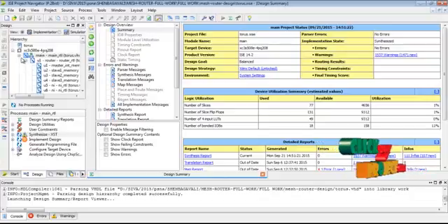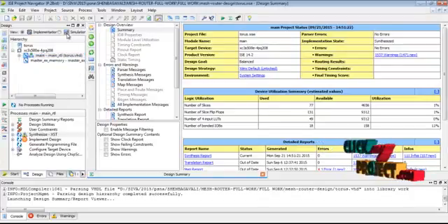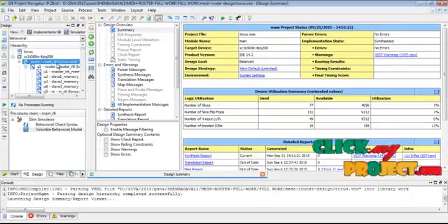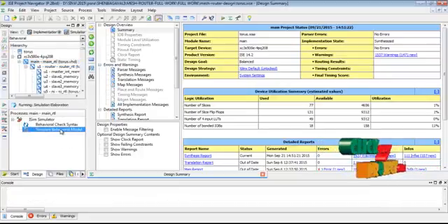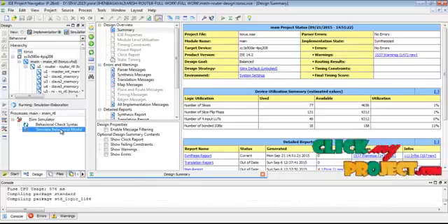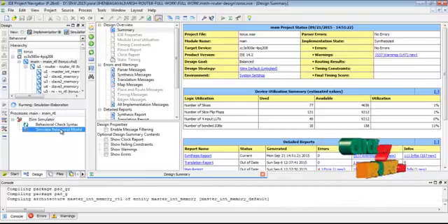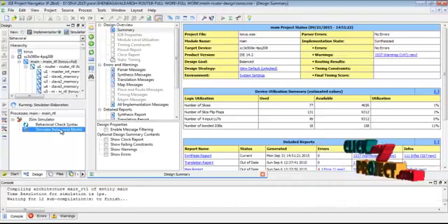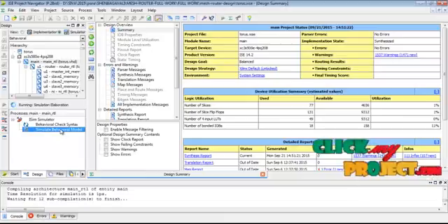This is the overall main design for our architecture. Then we select the simulator process, which simulates our overall mesh topology based NoC architecture design. This process was completed successfully, and we open the ISim simulator. This is used to simulate our overall NoC architecture design.